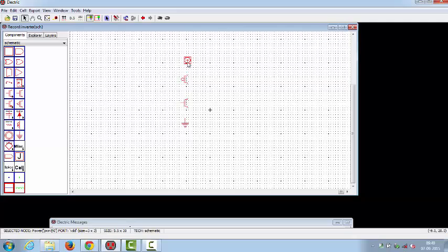Left click on the component to be connected and right click on the other component. This is how a connection is made. This connection is called a wire. Now let us connect the two gates of the PMOS and NMOS. This is our inverter schematic ready.